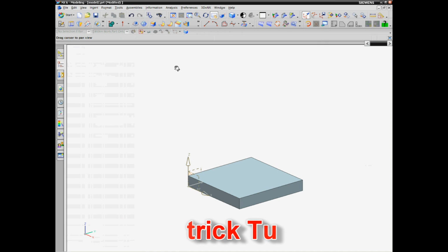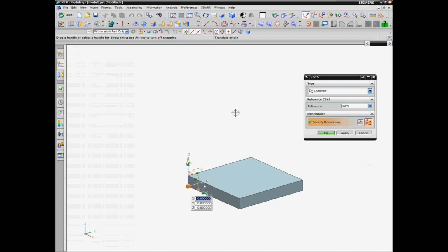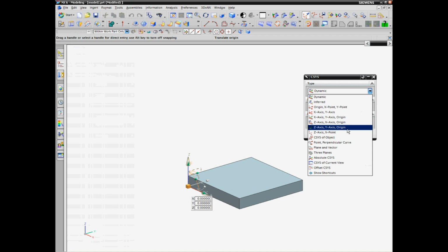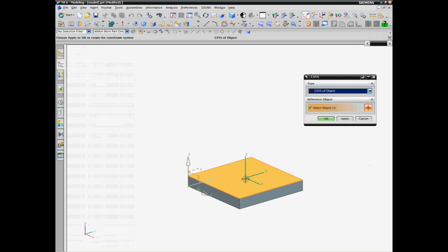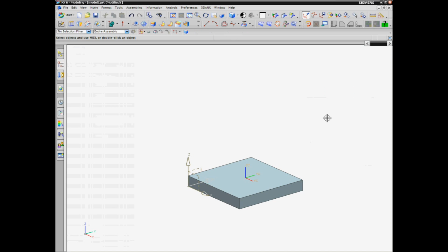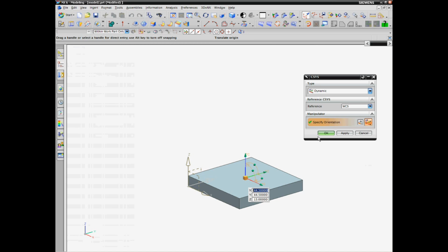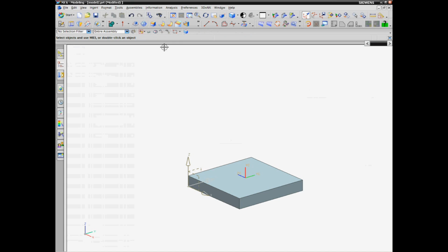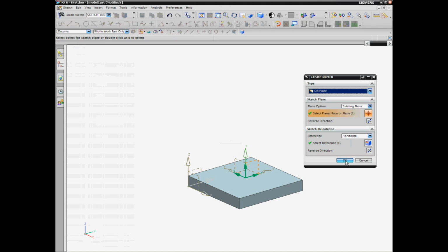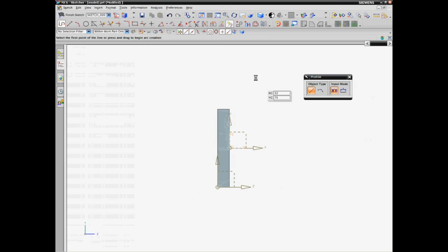We can then go in, position the geometry so that we have it centered. We'll now go in and manipulate the work coordinate system. We'll put it onto the coordinate system of the face of the base part we just drew. Now what we'll do is we will orient 90 degrees so that the X and Y can be used for a sketch. The sketch will be used to develop the center line for the pipe.